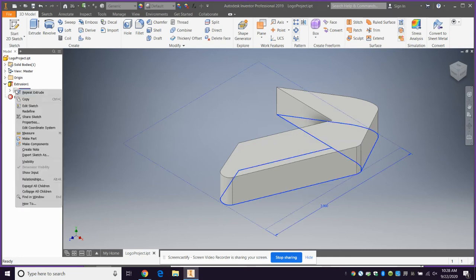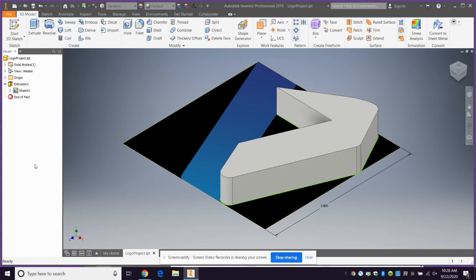Well, I'm going to right click on that sketch, and right down here it says visibility. If I click that, it'll bring it back so I can still see it. Now, what I don't like about this is that my extrusion kind of just blends together. I can't tell that those are two different parts of my shape, right? It's just this solid hunk.